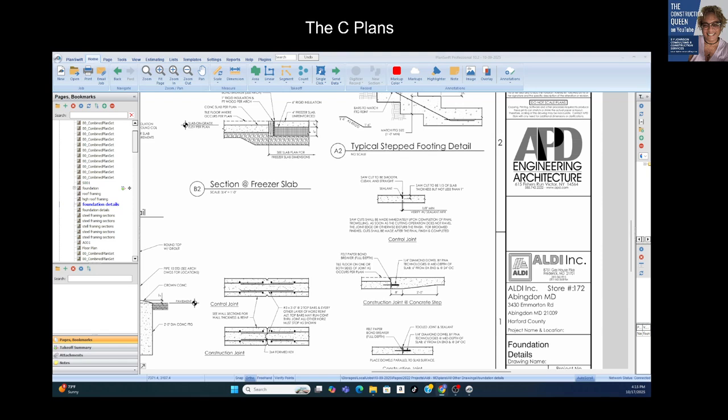And then I did mention piles, right? Depending on the type of soil the building is in, like at the beach or where the soil is unstable, like beachfront property, where you've got to get right down into the bedrock, there are no slab on grades there. And we use piles for those. Okay, so those are the types of foundations that you could possibly have.